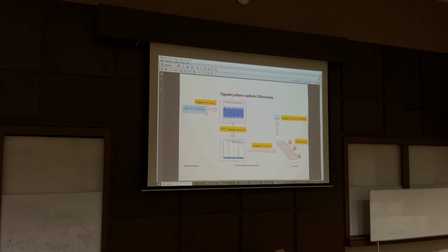But the signal, because of the transmission, is distorted, there is noise on it, and maybe some other frequencies. As I said, if you switch on a motor, because of this step input, there are a lot of high frequency components radiated and broadcast into the environment. And that is a disturbing signal, of course. So what you get is something like this.